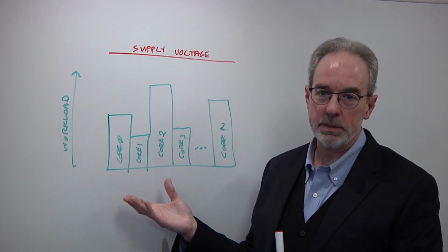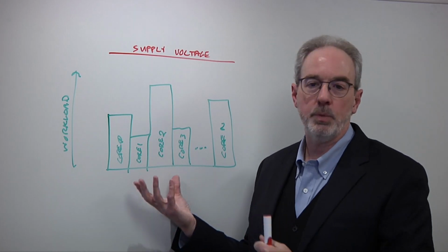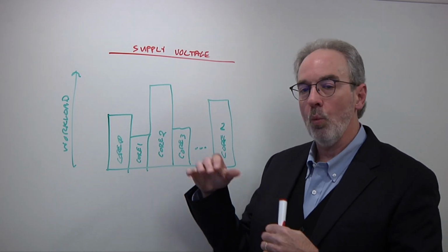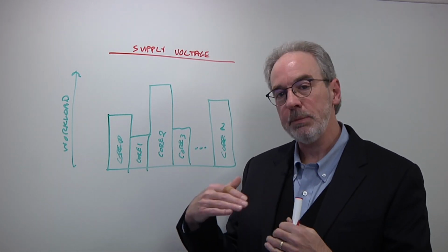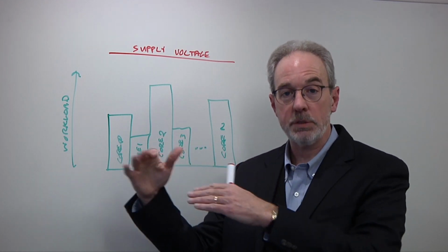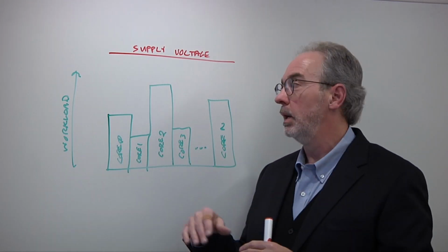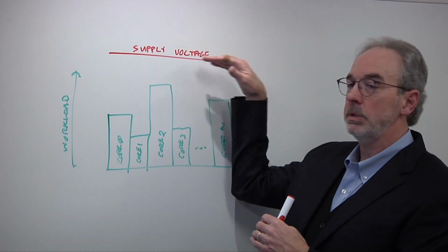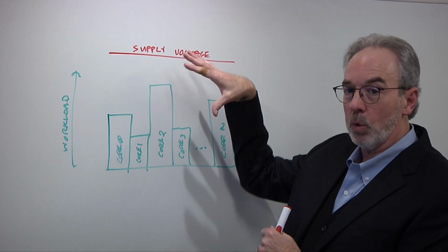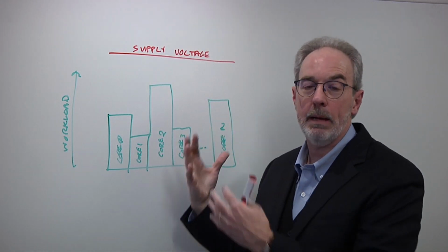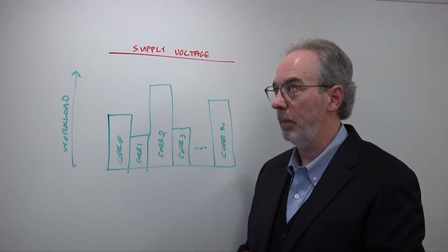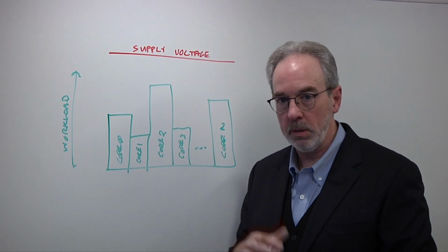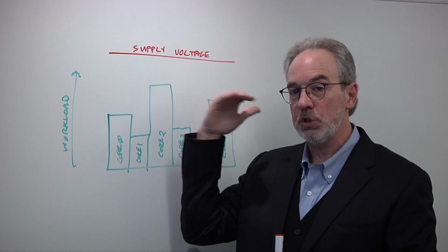This can be an array of processing cores or clusters within an AI engine. And when the power grid is designed, it has to be designed to meet the performance level that the customer demands, that marketing then demands, and the bosses demand. So you have to be able to design your power grid to take the worst case scenario of every core running absolutely flat out. And that's the design parameter. If you don't have the ability to manipulate that voltage, it's stuck there.